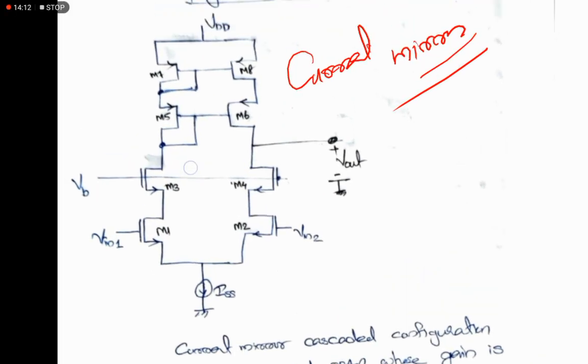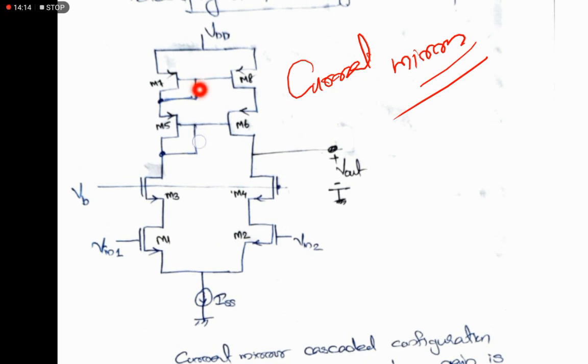And another one is the telescopic OPAMP with a single-ended output. For getting a single-ended output, we need to use a current mirror. So just observe that we are making the current mirror configuration in both the cascoded stages, and here also the derivation will be the same, gain will be the same, and overdriven voltages will be the same.